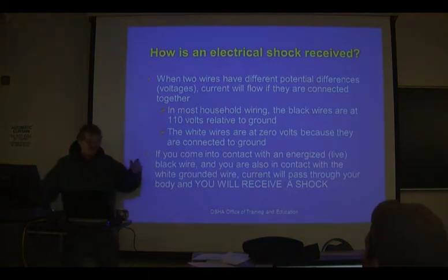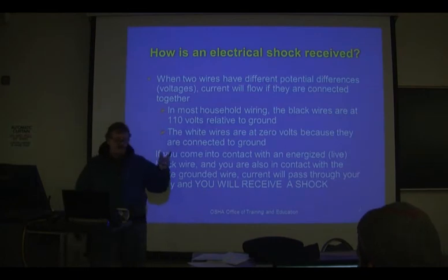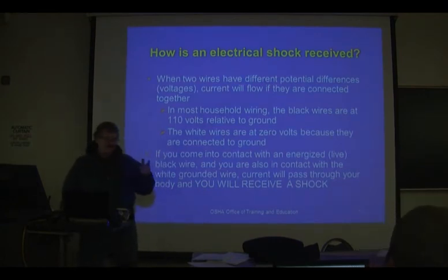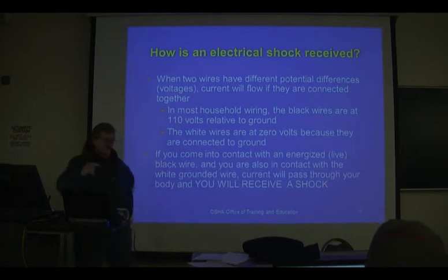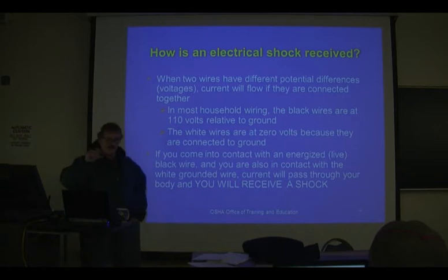Right. Most switches, when you turn a switch off, most switches only break one conductor, okay? And they break the hot conductor. If you turn something off, you break that connection through, say it's a light and you've got it wired up so white's to hot, black's to ground. It'll still turn that light on. And when you turn that light switch off, that light will still turn off because there's no path for current flow. But if you turn that switch off and then you stick your finger in that socket and you're touching the ground, now you've got the hot going through your finger to ground. So the light switch doesn't give you any protection, okay?